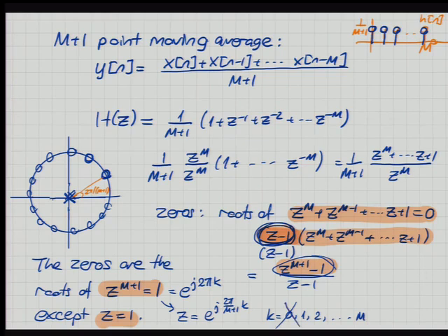So then, can you tell me what kind of frequency response I would expect from this? As I start at omega 0 and keep going, I'm going to visit 0 very often, right? Every time I'm passing through one of these frequencies, I'm going to hit 0 because I'm crossing a 0, right? So you'll start at 1.